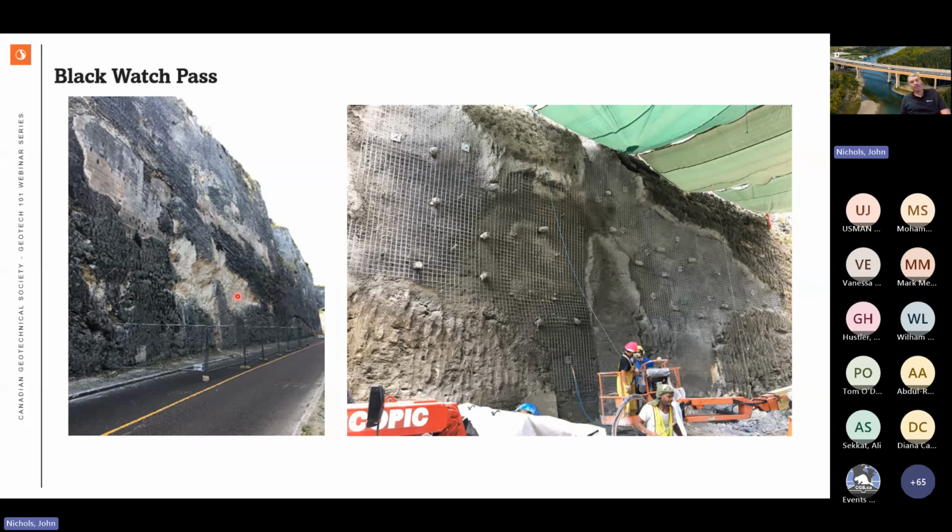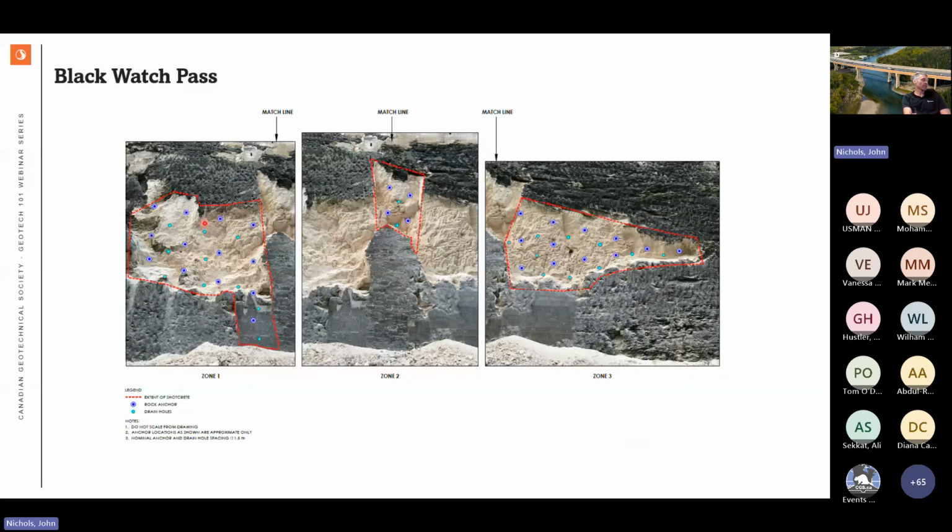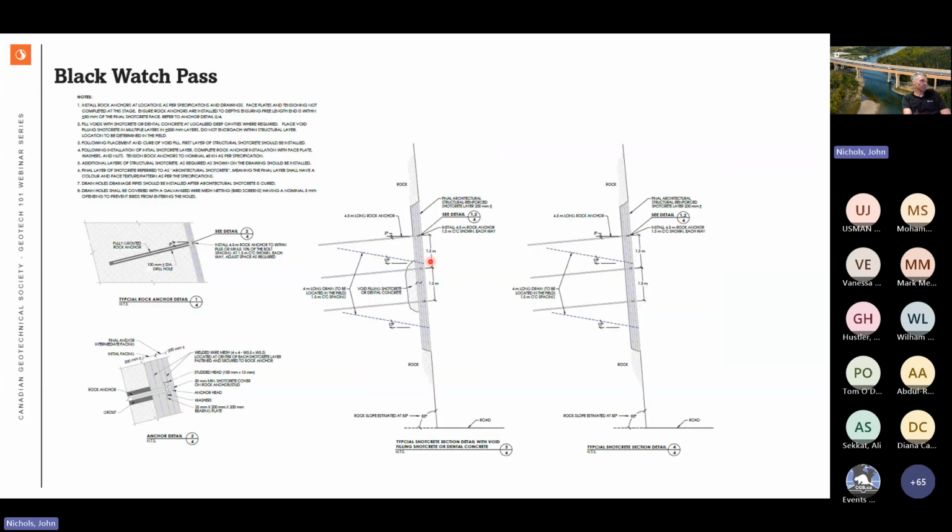But we knew that it had lots of water and drainage in the rainy seasons here, and that's what's causing this to erode, the way the water goes through the slope. So we had to come up with drainage throughout the site and some pinning. So that's essentially what we did. We came up with a rock bolting pattern and some drain holes and the extents of some shotcreting. And yeah, so this is the design.